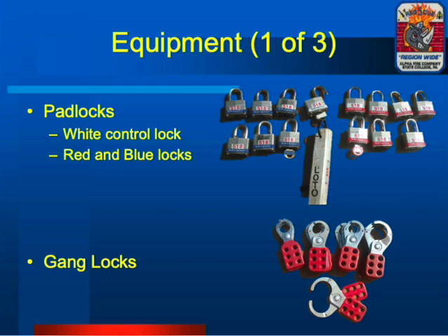Once the fire department is done with our operations, we remove our lock and we're free to go, but the facility still has 2 other locks on it. Now the device is controlled by both building maintenance and the electrician. And that device cannot be reactivated or restarted until all locks are removed, until all 3 people really verify that they're done working with that piece of equipment and it can go back into operation.